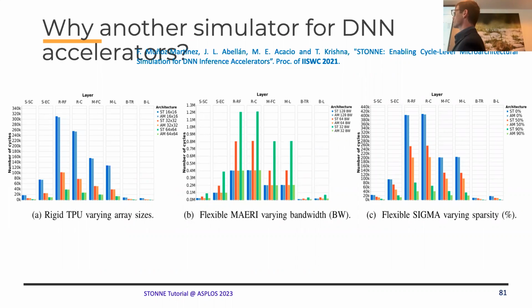And here, just to summarize, when we consider dense, regular computation, analytical models are very good, because you can see the bars in similar colors, blues or reds or greens, are matched more or less. But when you consider scenarios in which there are pipeline stalls, when you cannot guarantee that all the elements required, for example, for conducting the dot products are fetched at the same time in parallel because you don't have full bandwidth from the global memory, from on-chip memory, then you observe pipeline stalls, so the runtime is higher.